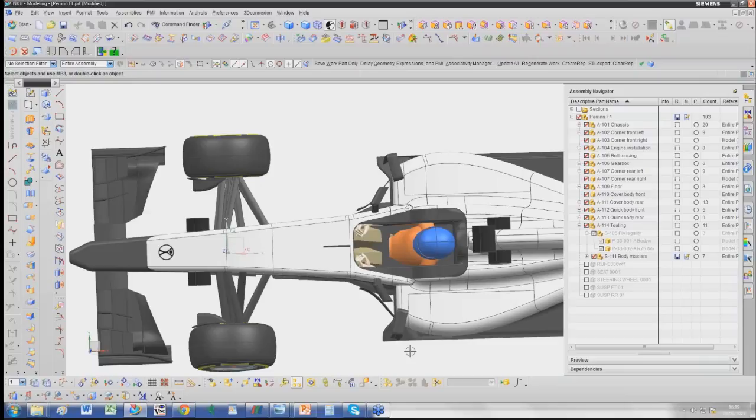And in the end, inlet just means that, you know, flow is going in. So you have a fixed velocity. In this case, I think it's 60 meters per second. And outlet means that the velocity is not fixed, but the pressure, that's the atmospheric pressure. And that's the reason why we set up like this. And we know it's not very, very easy to understand this from the beginning. That's the reason why it's ready to run simulations. But we have also a lot of tutorials and other stuff on SimScale, which you can access for free and to learn more about simulation and CFD in general.